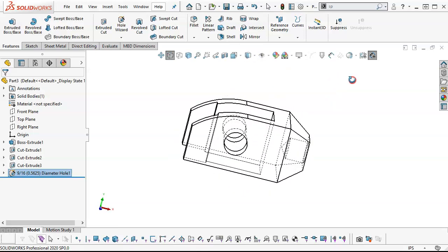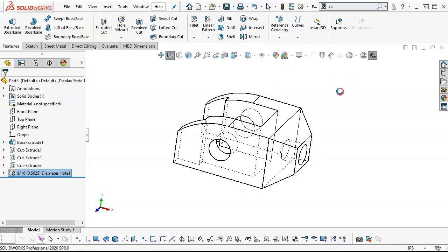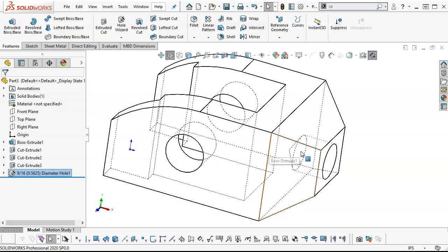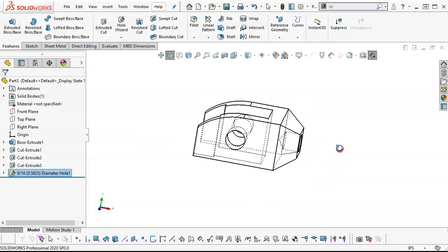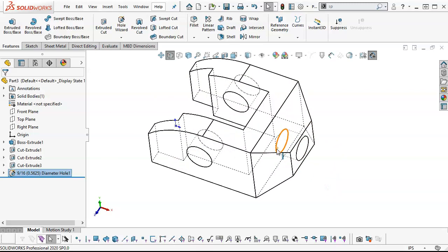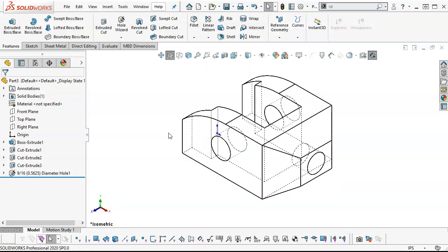Hidden lines visible, we're going to see that drill point. If this is mass, then I want to see that on the drawing. If this is just flat bottom, I can draw the circle, extrude it out 1/2 inch, and know that it's flat bottom. But from the manufacturing process, I probably do want to include that that drilled.